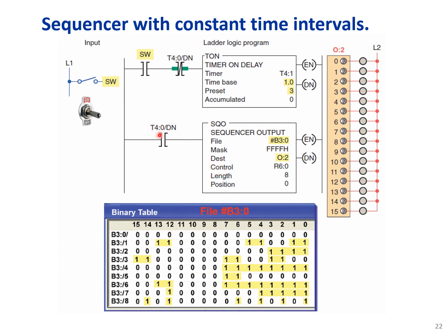So here, basically, when the switch is just to start the program, okay, so the switch should be on, and once the done bit of the timer is false, then this one becomes true, and it triggers the, sorry, this is on the second one.